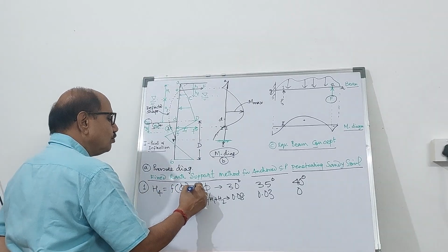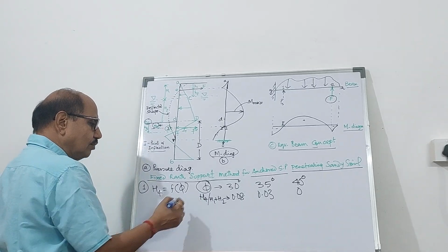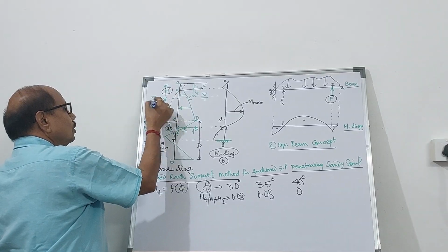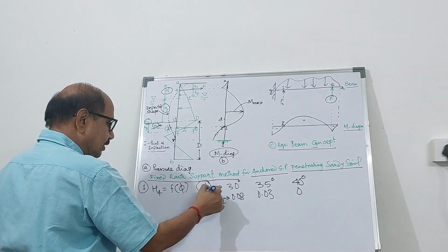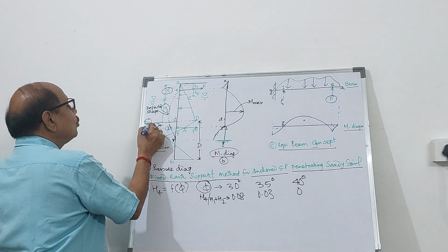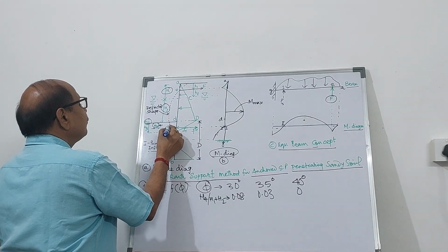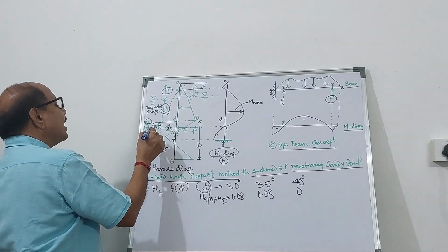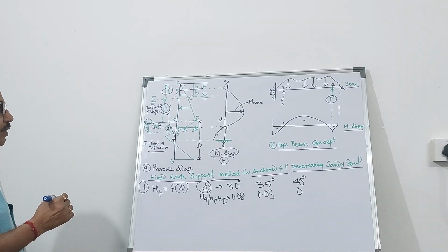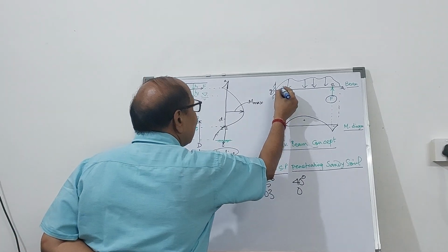So depending upon the value of phi, you can find out the value of H4. Both H1 and H2 are known to us. So the denominator is known to us, and therefore we can find out this value of H4. That means we can find out, from the dredge line up to the point of inflection, the height H4. Having found out the value of height H4, now between I and E,